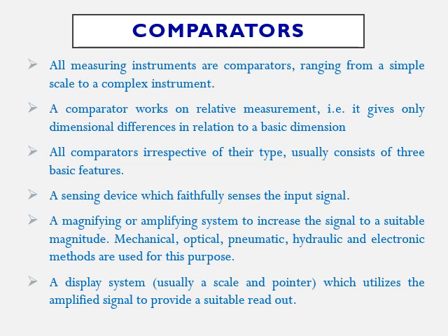When we restrict ourselves to measuring instruments, let us go with an ammeter or a dial gauge. If I take the example of a dial gauge, a plunger comes out of this dial indicator. When the plunger is pressed, that displacement we give to the plunger is the input signal, and it is amplified with the help of a spring behind the dial indicator scale.